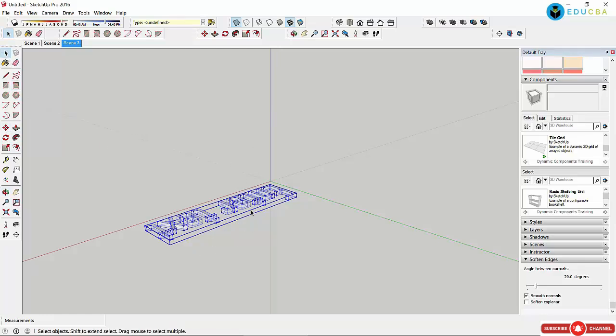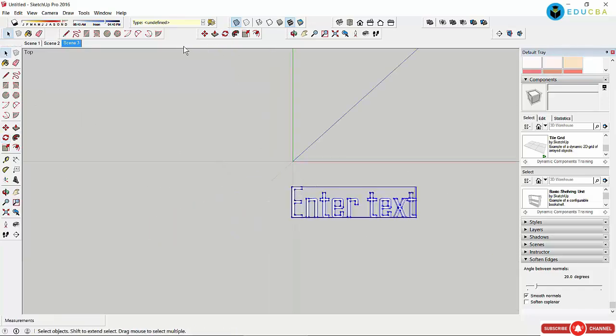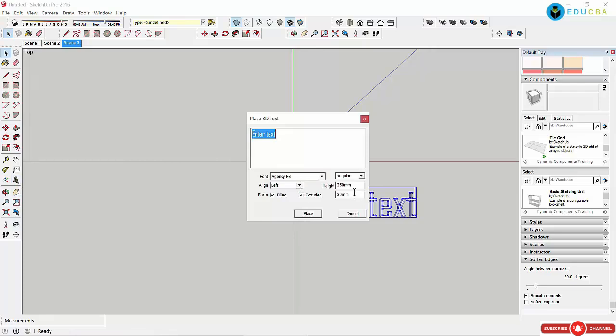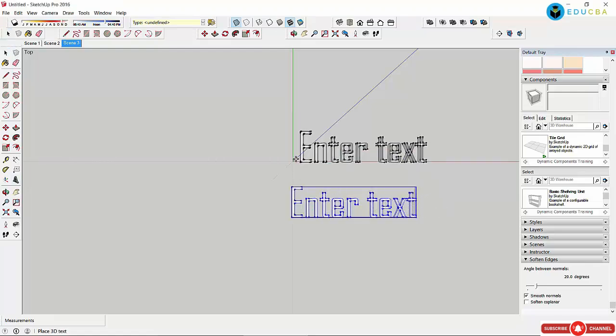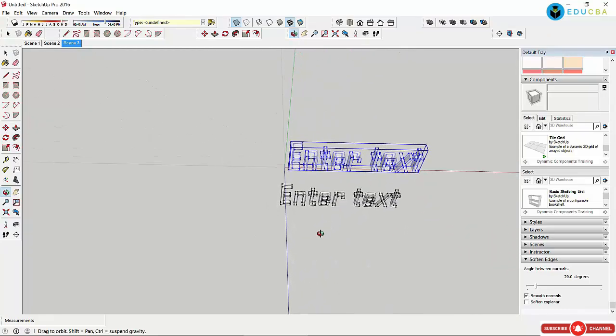Now here it comes in the y-axis. You can rotate and reposition it with the protractor tool, vertically or horizontally. When you create text only, its parameter and extrusion are already defined. Height, I make it 60 mm. When you look from the perspective view, you can see the height here is different from the height there, 60 mm. The extrusion factor is more.